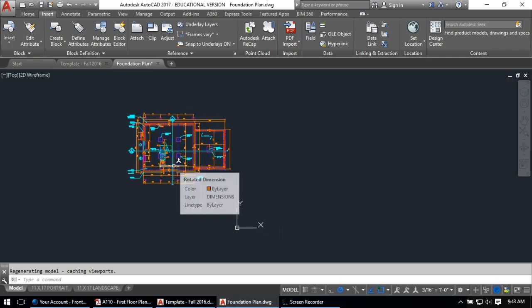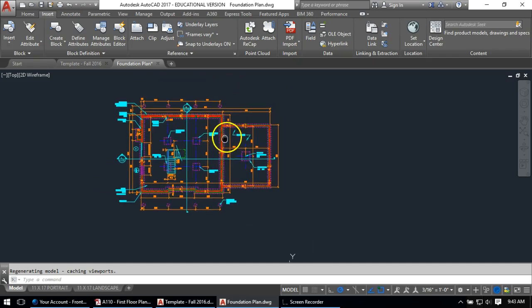There are lots of ways of doing this in AutoCAD, but what I essentially want is the exterior walls of this foundation. I'm going to copy those, as well as my section tabs and my stairs, over to the right hand side because those will be the same for the first floor plan. So I'll be able to start drawing with content already there, and all the exterior dimensions that you see on the plan, of course, are going to be needed to build the house, but I won't have to redraw all that work.